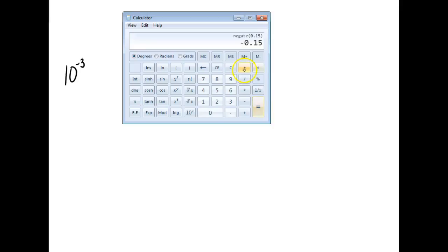Okay, I'm going to change the sign of that, and then I'm going to raise 10 to that power. 0.707. If I did minus 3 dB for power, I'm going to say 3, divide that by 10, because here we're dealing with power. And then I'm going to change the sign, and I'm going to raise 10 to that power. Should give me 50%.